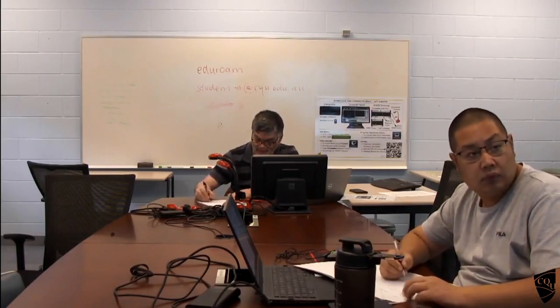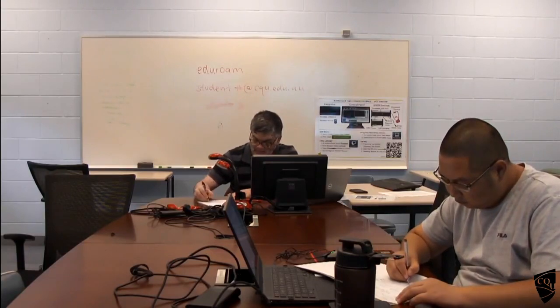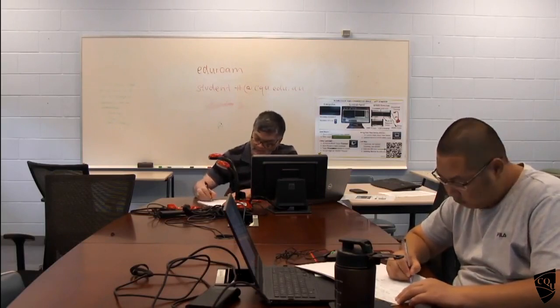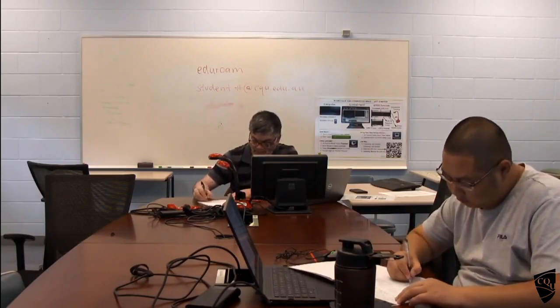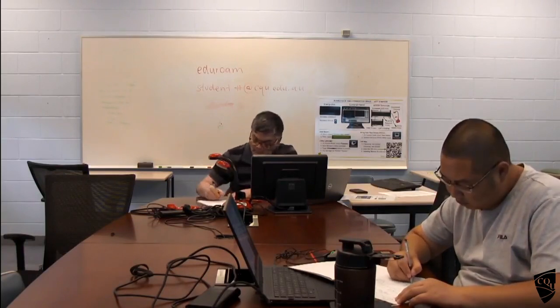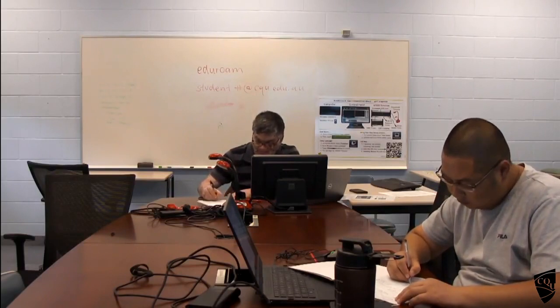So A_i y_i is B D squared by 2, and (n minus 1) d A_st. I will add these: B D squared by 2 plus (n minus 1) d A_st. I will also add the areas: B D plus (n minus 1) A_st.